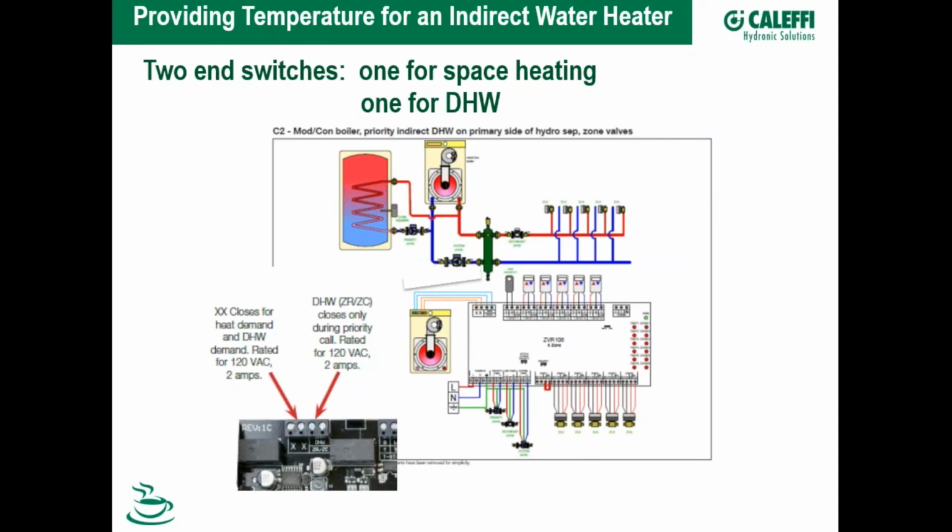The problem doing this application with particularly a high loss heat exchanger is, if I size the circulator here for that 8 GPM, I bring the system circulator on, and because of the increased head loss, now I'm trying to parallel two circulators through the boiler.